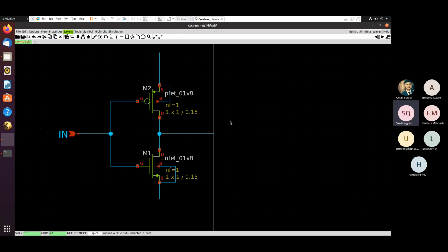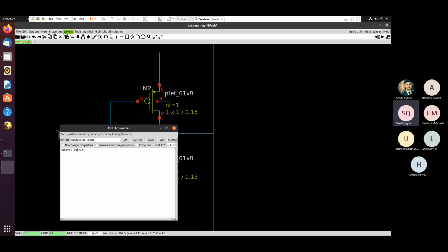So we have now created an input port. This is the interface for this schematic. And you see as well that it is P1, so the port numbering is 1. You have to be aware that the ordering of the ports should be consistent with the symbol.